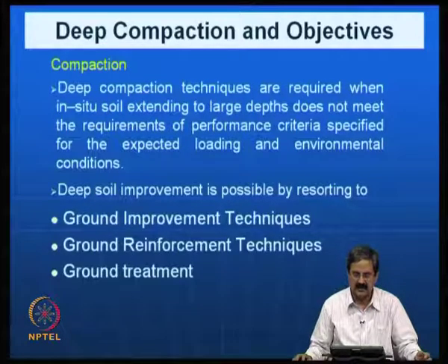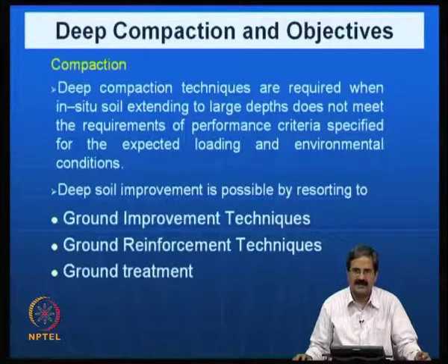Deep compaction techniques are required when the in situ soil extending to large depths does not meet the requirements of performance criteria. For example, in places like Kerala and the east coast, west coast, in some areas the soil is very soft, and if you want to construct some infrastructure on them, the settlements are going to be huge and they do not have adequate bearing capacity.